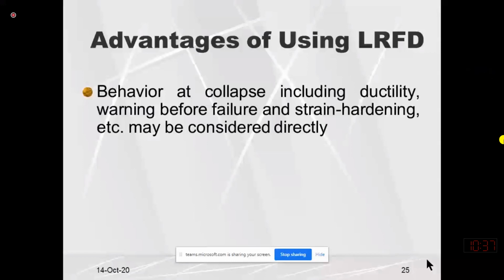But here, for example, in tension member design, we are considering the capacity with phi value 0.9. 0.9 Fy means that if the yield strength is equal to 250, we are considering the failure stress 225. It means that our failure limit is very close to the yield value. So if we are overloading it, there are chances that some part of the material will enter into the yield zone.